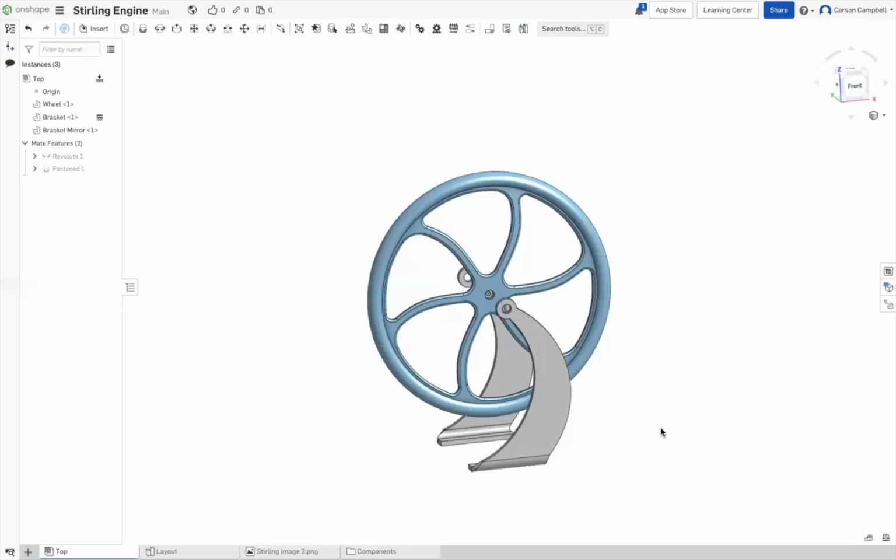In a larger design, I could have a group of parts that are related. I could have another group of parts that are related and another group of parts that are related, and they all roll up into an assembly. I'm designing in the assembly, and I'm controlling the creation of all my parts. I can create all the parts individually like they did in SolidWorks, and that's a mess. Or I can create bunches, groups of parts inside of part studios, and then I can roll them up to the top.